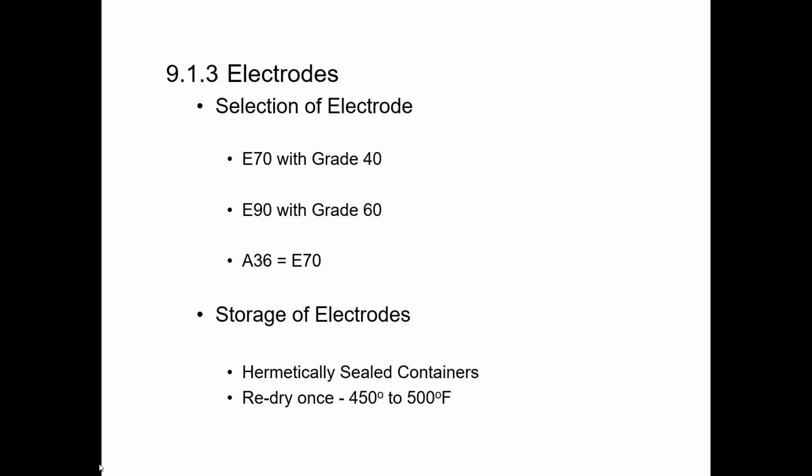It's important with welding that we take care of the materials that we're using to weld, namely our electrodes. So the way that we store those, the way that we use them, the ambient environment, it's really important that those electrodes are not kept in a moist or humid environment. They should be purchased and stored in hermetically sealed containers. And then once those containers are opened, it's required that they're stored in a very specific type of environment, so that they remain dry.